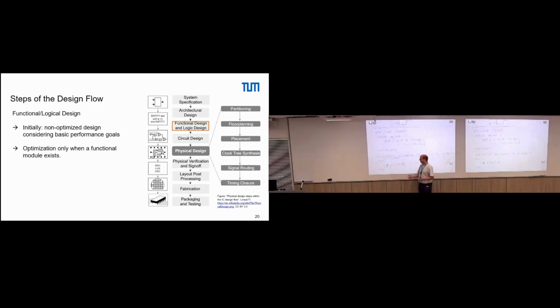And the tool that compiles makes out of this a circuit where it just says, okay, I have an AND gate, just as I did here. I have an AND gate, I have A, I have X, I have C. I have another assignment here, which is B. And X is assigned to B, so we need this connection. So this is what the tool effectively makes out of that. This is how it works, or what happens in hardware then.